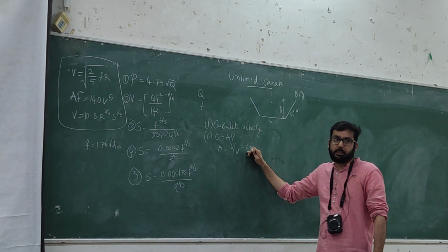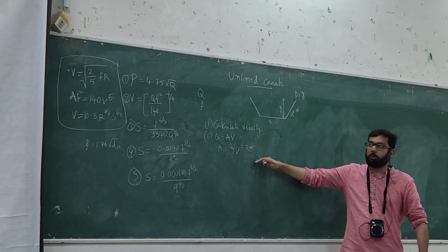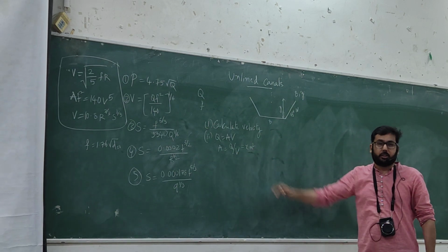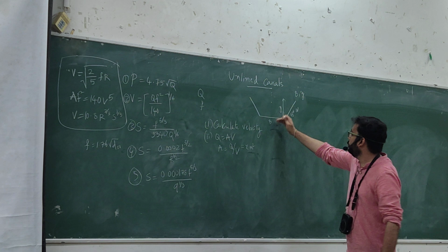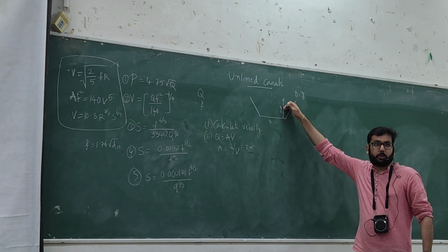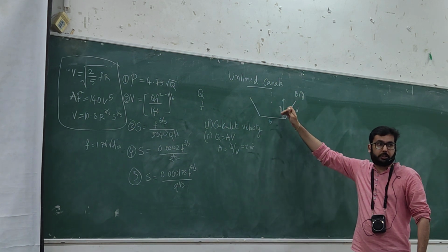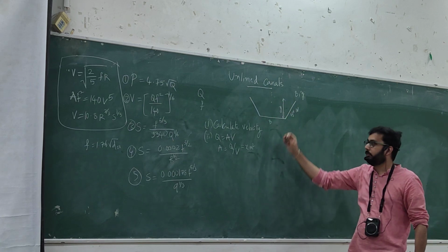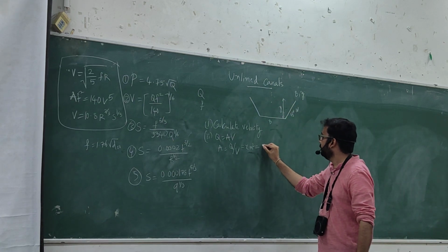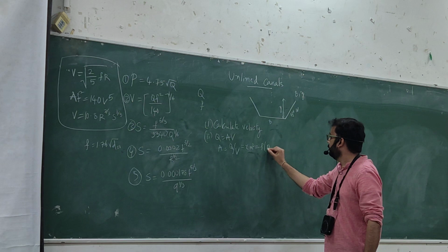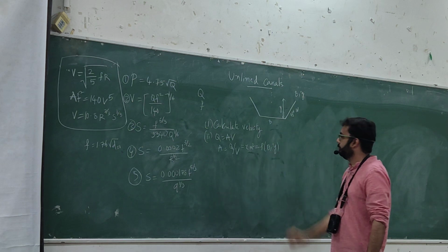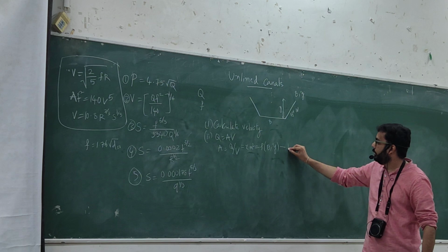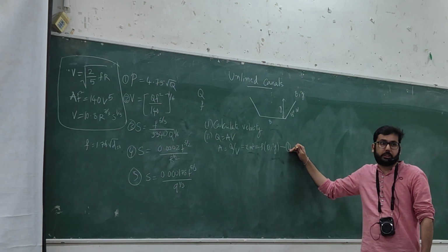Let's say we get some x meter square. So we know the discharge, we have the velocity, and we get x meter square. And we also have two unknowns, B and Y. So you can also calculate the area based on the trapezoidal section with the two unknowns, B and Y. So this is one of the equations that we arrived at.